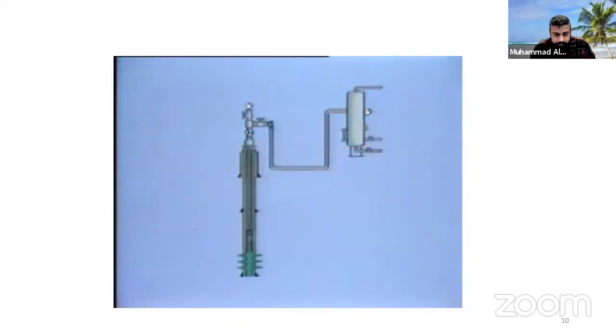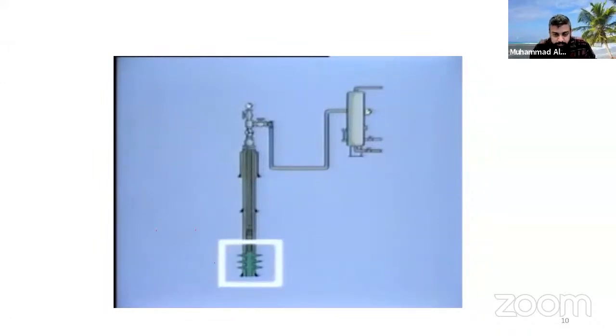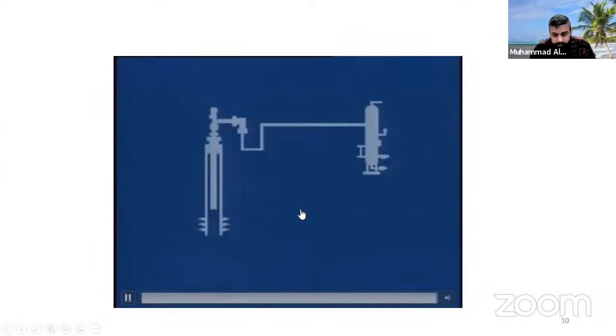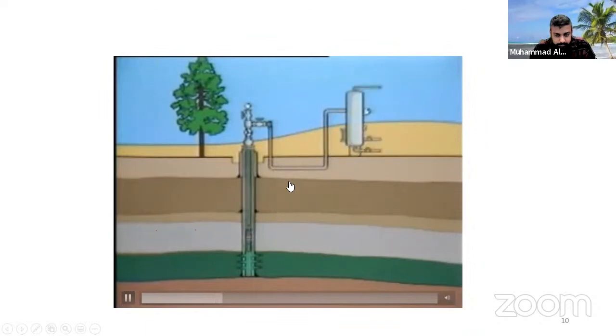All of the components are interrelated. We understand intuitively that fluids cannot be produced on the surface at a higher rate than they flow out of the formation or are lifted up the tubing. So we as production engineers manage this. We know that fluids flow from points of high pressure to low pressure. What we must do is show graphically how the pressure and flow rates for our system are related. We begin our discussion by dividing our producing well system into its major components: the producing formation, tubing, choke, surface flow line, and separator. These elements are sufficient to illustrate the concepts involved in describing the pressure flow rate relationships of our production system.